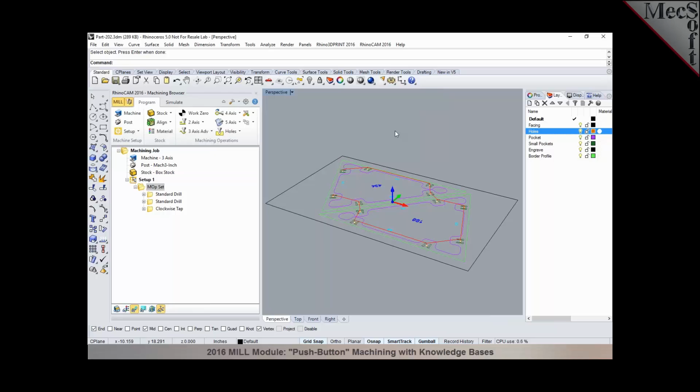In this particular case, you wanted to do a spot drill, a drill, and a tap operation. Since the geometries are going to be exactly the same for all 3, you can just assign one rule, and the rule can be applied to all the operations in that specific knowledge base. So this is also a very nice, powerful feature set, where you can assign the same rules for all operations, and this would be an ideal example where you would want to do that.